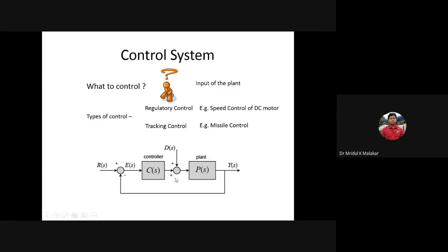This is actually called controller parameter design. Once you get a set of parameters, you have to tune the system. The physical system has a mathematical model, and from the mathematical model you get very neat and clean signals. You know the disturbance pattern you are giving, and accordingly you tune the KP and KI values of the PI controller in the software.